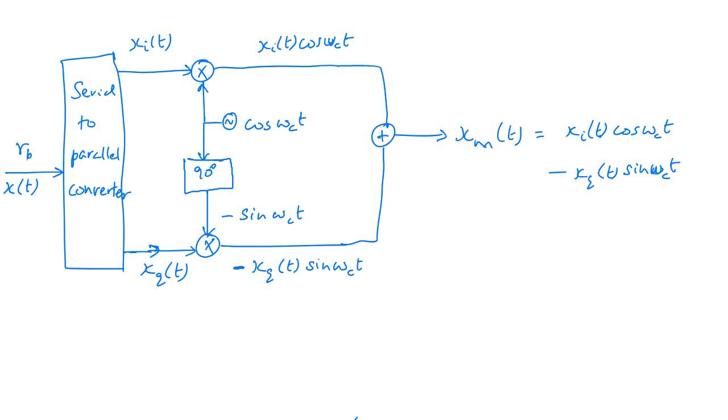Because we have now two carriers, we can represent the cosine carrier with only two amplitude levels and the sine carrier also with only two amplitude levels, and with these two we can have a combination of four symbols. For example, the cosine carrier can have an amplitude level corresponding to a binary 1, and the sine carrier also can be a binary 1. So 1, 1 or 1, 0 and so on.